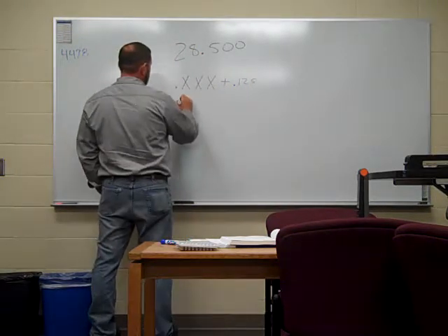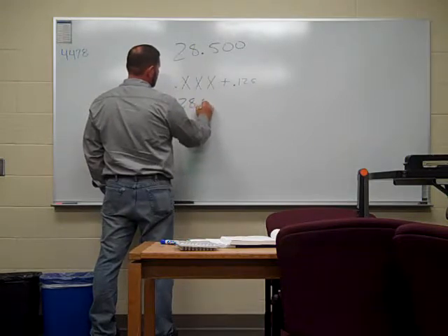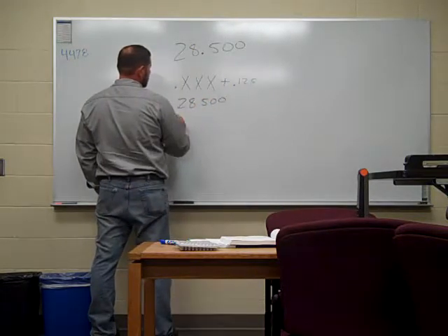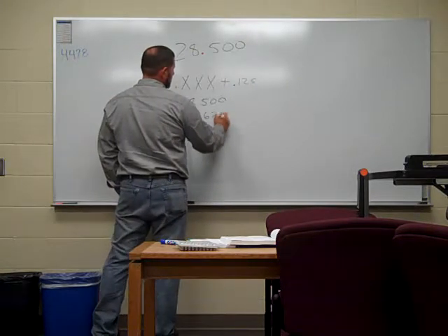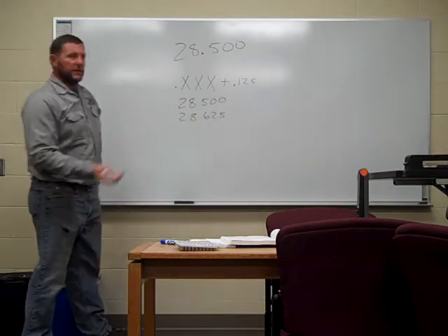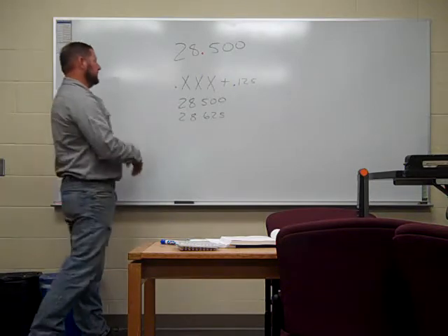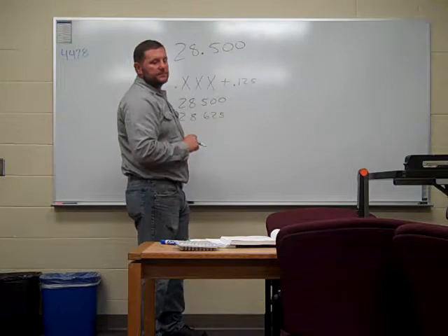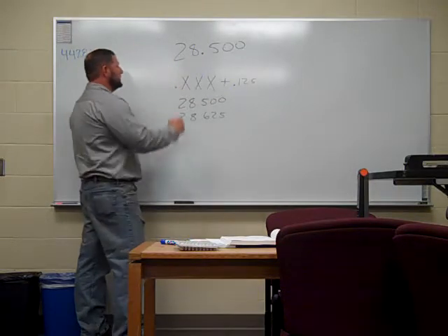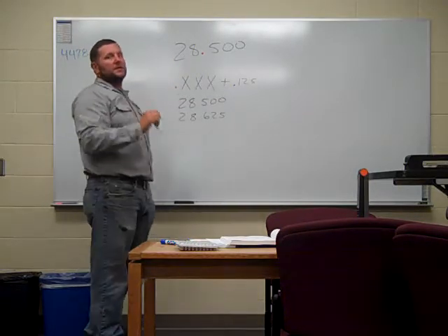So what's my range? It has to be at least that big, up to that size. Or just vice versa. If there's only a minus, you're only going one direction with that tolerance. Very important. This is always given to you in the title block, the general tolerances.